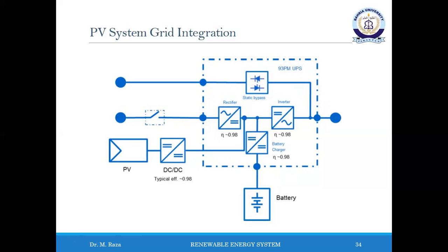This topology also provides the possibility to integrate the PV interface into the same hardware platform with the UPS and energy storage. Reducing power cabling and connection also improves total system efficiency. Typical efficiency for the DC-DC converter in the PV interface can be as high as 98 to 99%, and it can be integrated both electrically and mechanically directly to the DC link of the UPS.